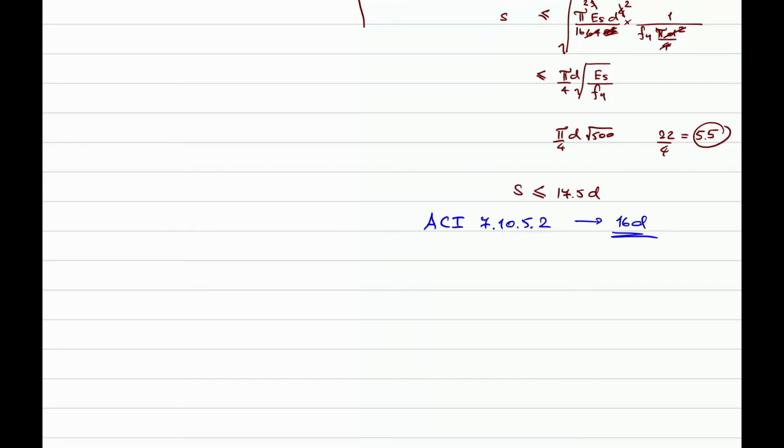But for high strength steel and slender columns, the higher the strength, the less the parameter, so it will be reduced. Higher strength and more slender column. For a more slender column, okay,